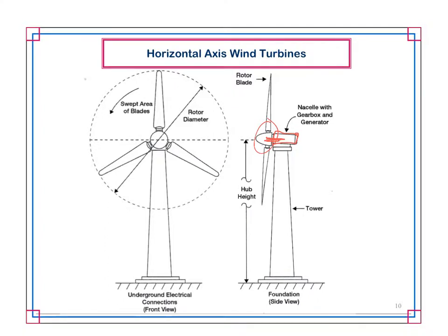That's a completely separate assembly that you can detach and reattach, and that's mainly for construction. It's easiest to erect the nacelle first because it's the heaviest weight, and then you erect the hub with the blades on after that. And usually what you do is you put one blade on, or maybe two blades depending on who you talk to, and then you tilt it up, and then you put the third blade on, and you do that sort of at a lower level, and then you just basically attach it to the front of the nacelle. The rotor diameter makes sense, right?